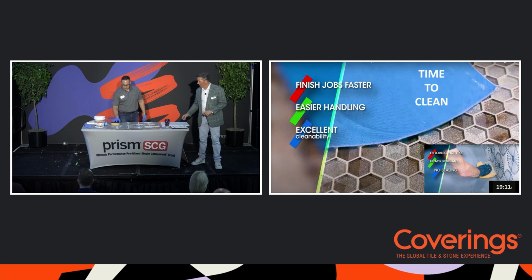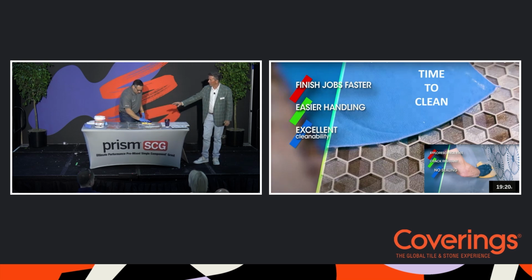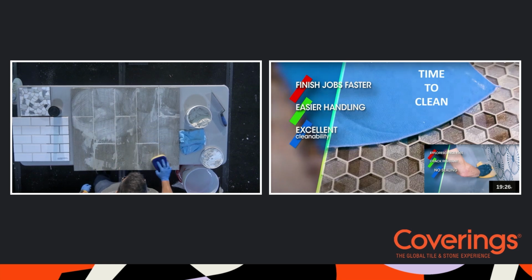So now, if you would, go to the camera, and we've installed some grout here. We installed some early, we installed some later, and he just recently installed some. So some of the benefits of this second gen material is I can install and clean right away. Why would that be valuable? Because I cannot do that with cement or epoxy.